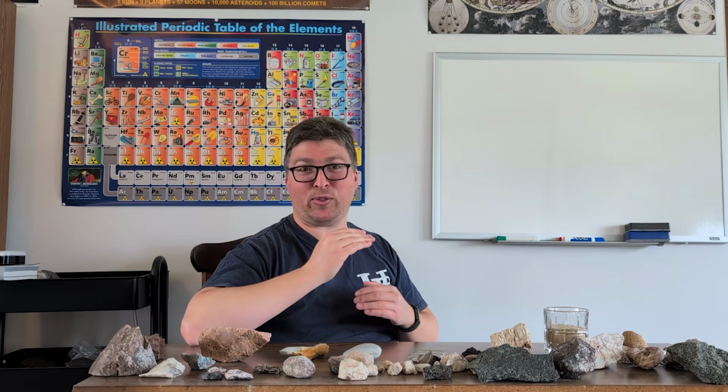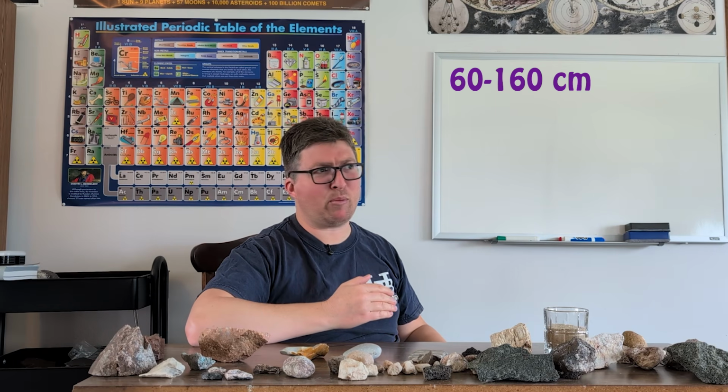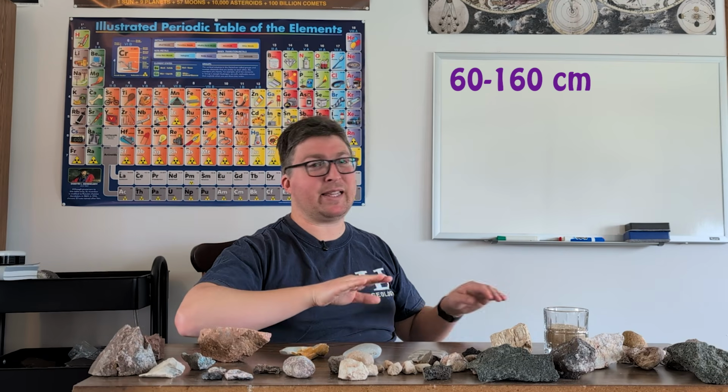In fact, if you take the inverse of hydraulic conductivity, it tells you how long it takes for a fluid to move through the material. And it takes about 1 billion seconds for water to travel 1 centimeter through most clays. 1 billion seconds per centimeter. That's kind of insane. And keep in mind that they're putting down a layer of like 30 centimeters of clay, probably minimum in most cases, to line these landfills.